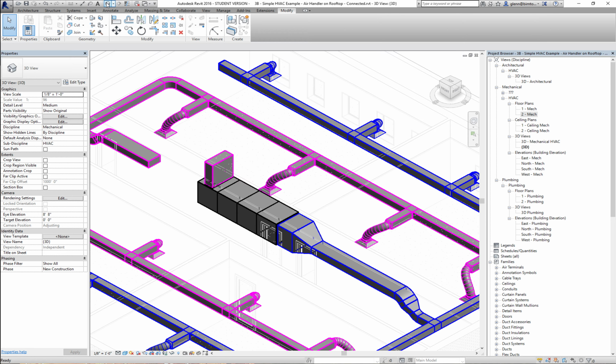Now, it looks like a very big transition right now, but I'm betting after I resize my ducts, this one coming in is going to be a little bigger, so it's not going to be quite so bad. This will tend to work okay, unless something turns inside out. If this pipe, or duct, ends up being bigger than the connector, then I might have to resize it to be a bigger unit, or do something to change the opening over here.